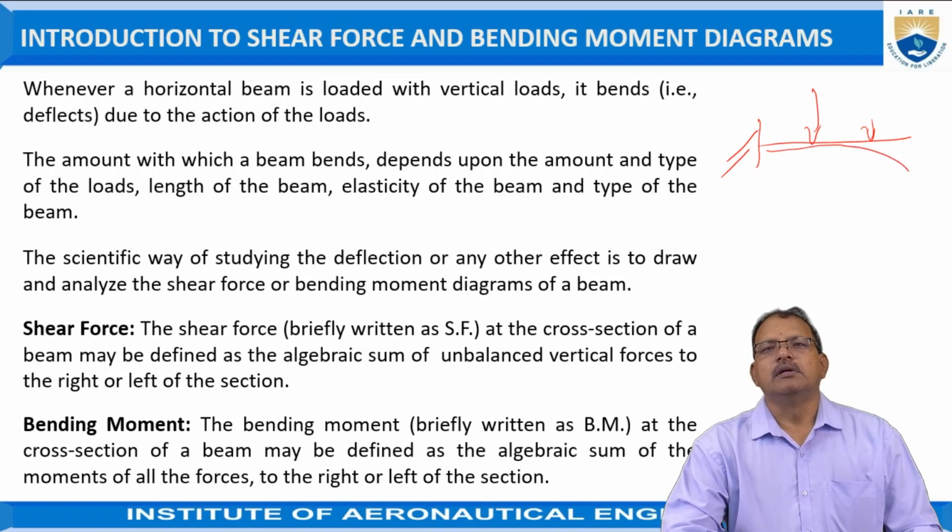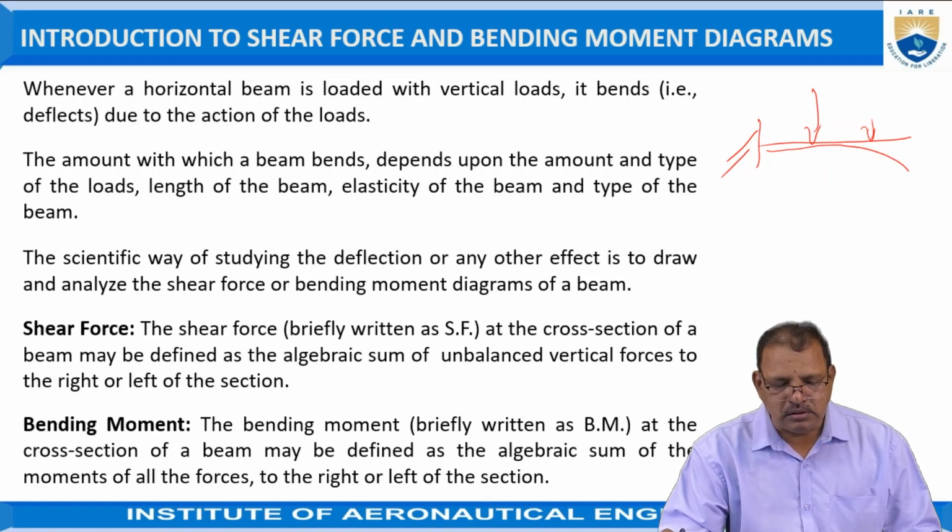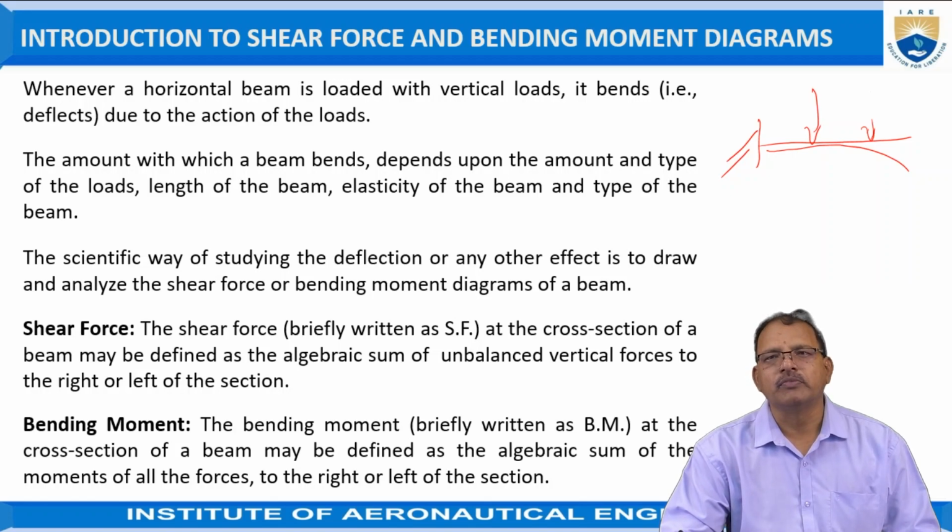The amount by which it bends depends upon the magnitude of the forces that are acting, the length of the beam, the elasticity of the beam, and the type of the beam. The scientific way of studying the deflection or any other effects due to the action of the loads can be analyzed perfectly by drawing shear force and bending moment diagrams.